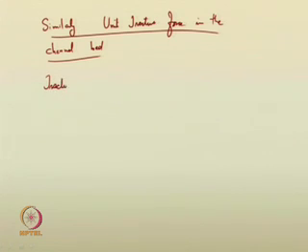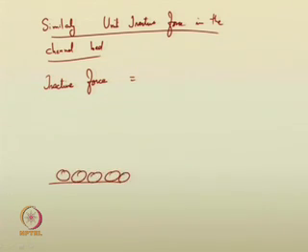Say this is the channel bed, there will be soil material particles of any shape. So, the tractive force acting will be the effective area of the particle into the unit tractive force in the longitudinal direction, or sorry, on the channel bed.